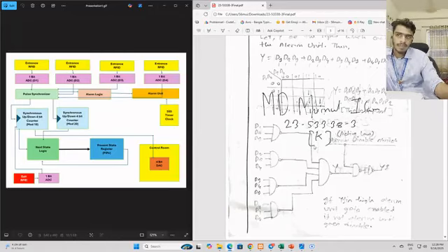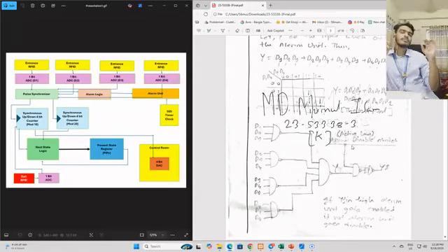And see, there is a manual disable switch, and this is an active low switch. If you press it, giving 0, that's the active mode of this button. If the alarm is already triggered, we need to turn off the alarm, right? That's why I placed the manual disable switch here.